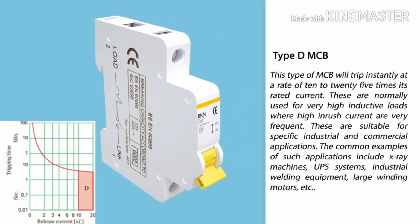Type D of miniature circuit breaker. This type will trip instantly at 10 to 25 times its rated current. These are normally used for very high inductive loads, where high inrush currents are very frequent. These are suitable for specific industrial and commercial applications. Common examples of such applications include X-ray machines, UPS systems, industrial welding equipment, large winding motors, etc.